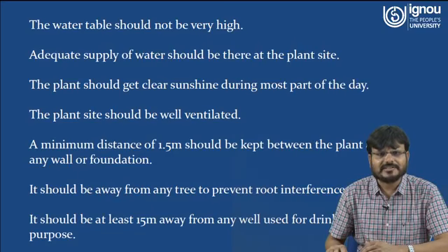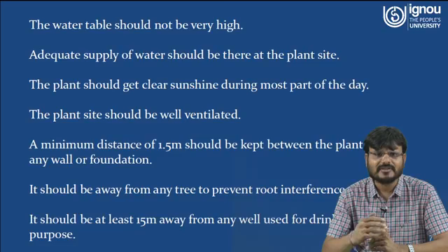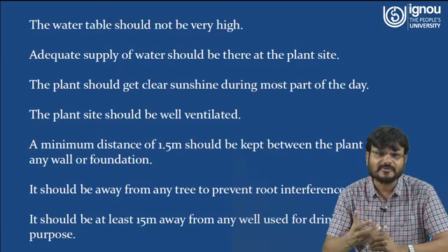The plant should get clear sunshine during most part of the day. Why is it important to get clear sunshine? Because this sunshine will heat the temperature of this slurry. If the temperature of this slurry is higher, that means fermentation will be more. If fermentation is more, that means you will be able to get more gas.